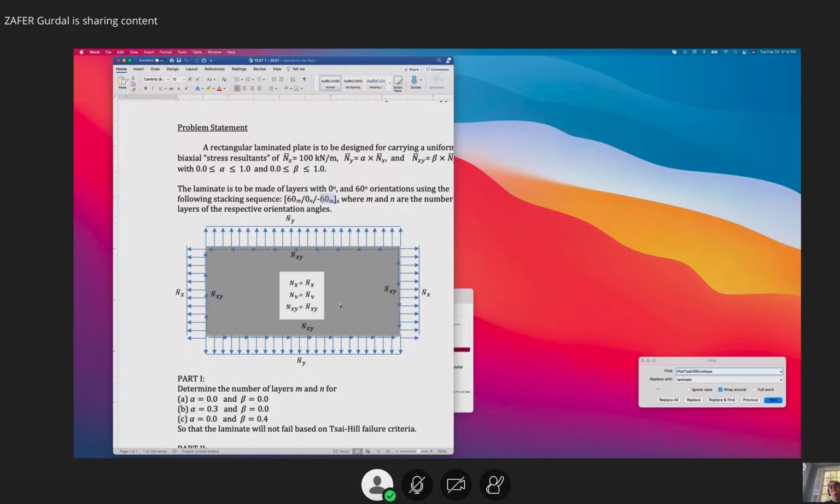And with the shear, it will make the problem even more interesting. But I didn't want to make it any more complicated than this, because even enumerating 3 variables can become a major task. So we used only 2 layers so that you can start checking M and N for every combination as you increase the thickness of the laminate.